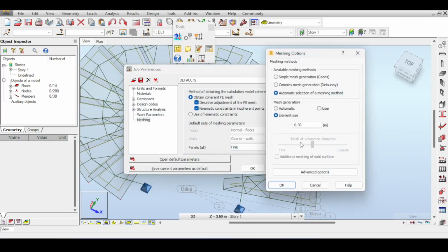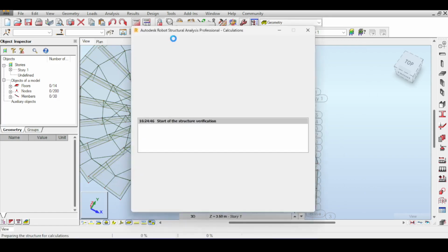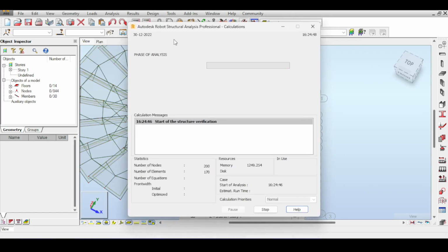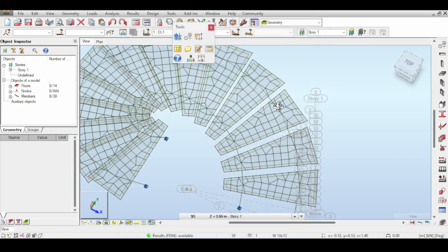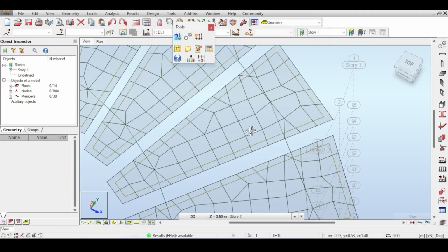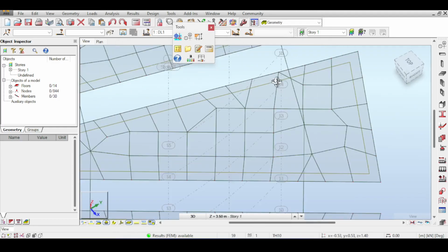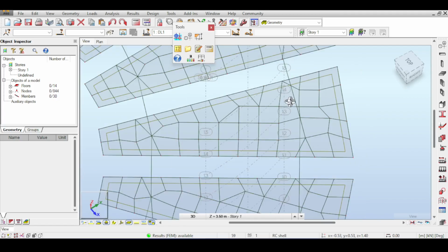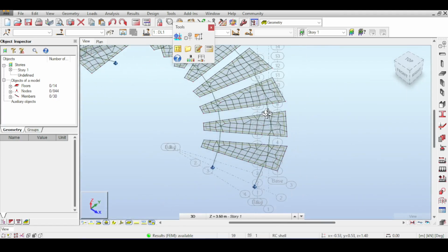Okay, let's go to advanced. Let's force it to use 0.1. Of course, this will now annoy the mesher, like, badly. But well, let it work. Yeah, I think now it's a little bit better. I'm still annoyed about those things. Those aspect ratios are not really that bad, but it's not optimized, to be honest. There is more we can do.